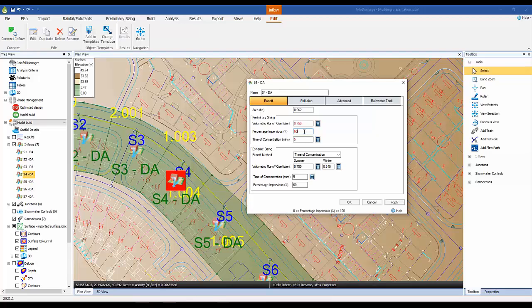One of the things also, which is really important at this stage, is this volumetric runoff coefficient. I could do a whole presentation just on this value, but essentially what we're saying is that once rainfall lands on this catchment, we're only going to consider runoff from 60% of it, because we only consider the runoff from the concreted and tarmacked and developed areas. And of the rainfall that lands on that 60%, only 75%, or a factor of 0.75, gets into the manhole.